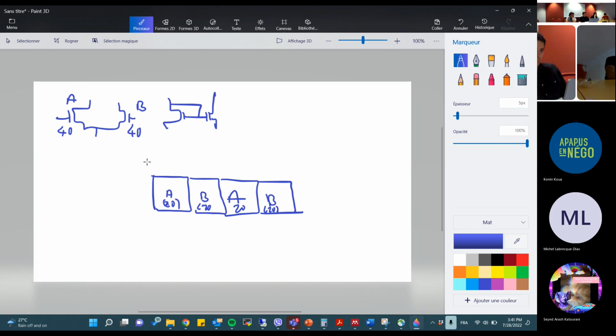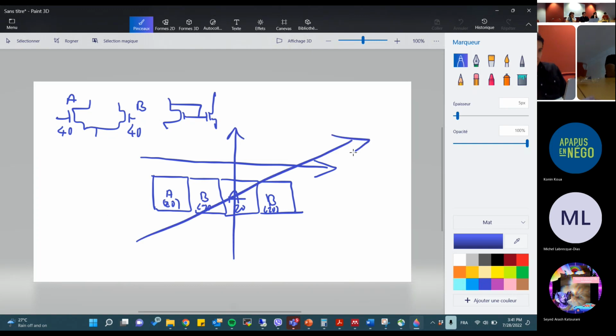So usually for mismatch and so on during the fabrication process, you can have some gradient. For example, the doping gradient in that direction. You can have a gradient in any direction: in X, in that direction, or in that direction. This is why usually we use a centroid structure, which is the most perfect thing for matching. If you take the structure A and B from a center point, you should see exactly the same thing. Is it clear so far?